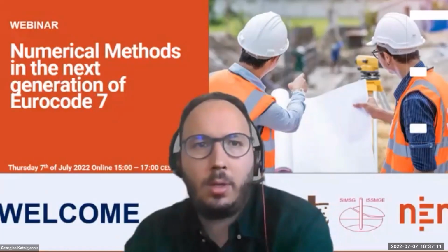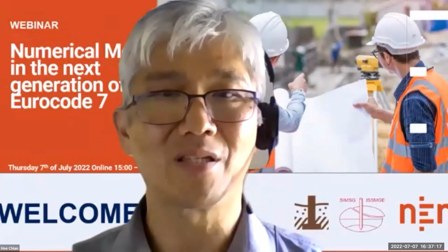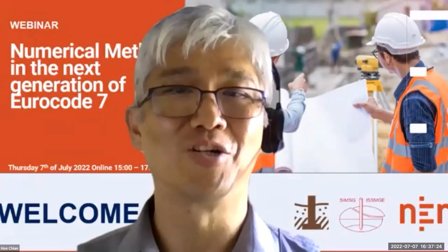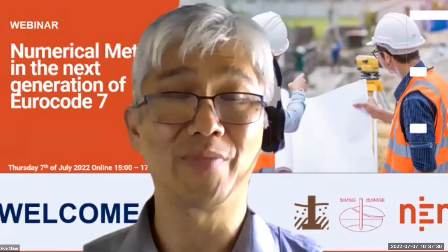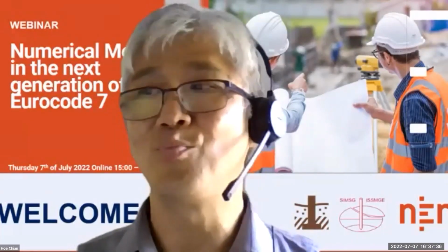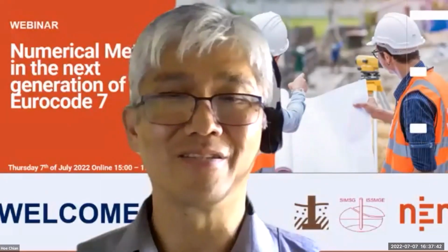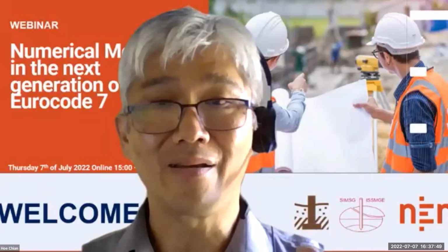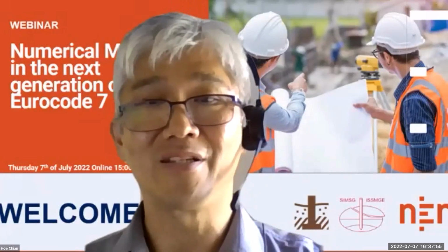I think that's exactly what you said, Jorge, no? Well, what I say is clear. It doesn't mean that combination 2 is not critical. Combination 2 can be critical depending on the soil type and how you build the retaining structure, and that's why I put the red warning there. Based on the conditions that I presented, in terms of ground conditions and construction sequencing, combination 1 has been critical for both the cases, but it doesn't mean that is always the case.